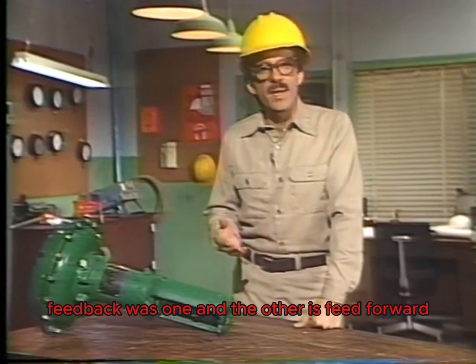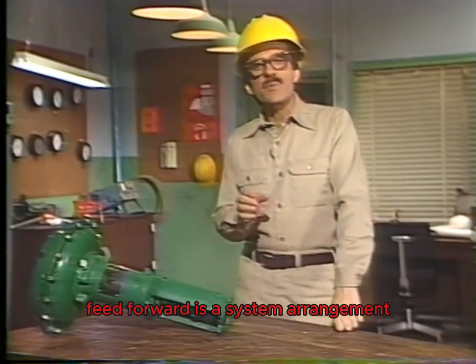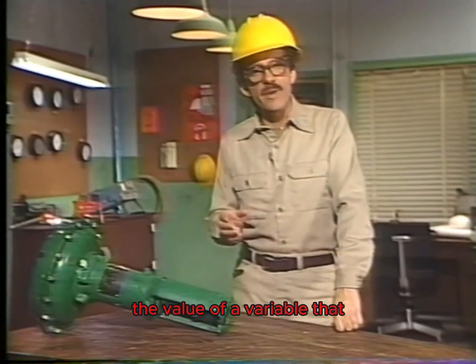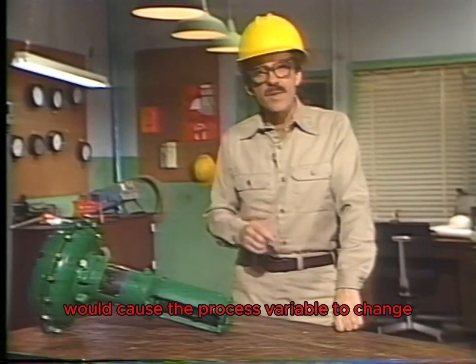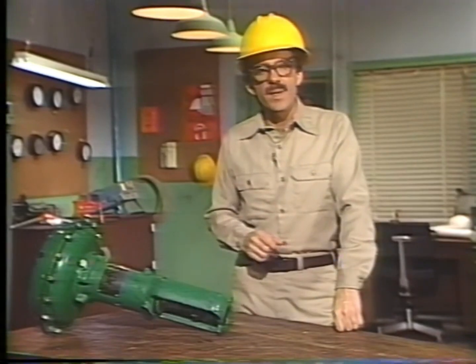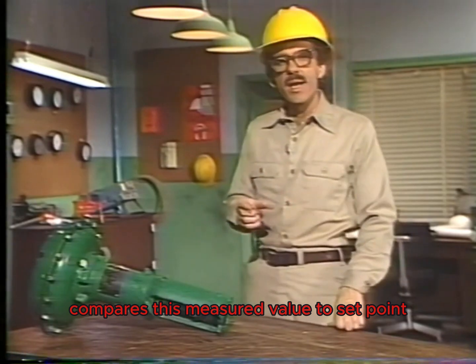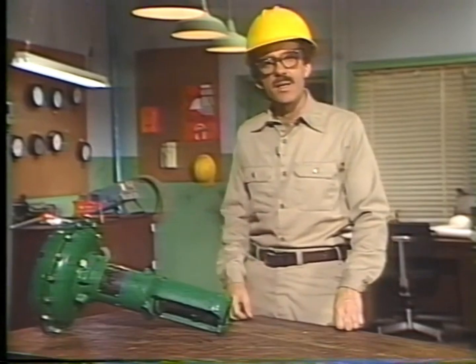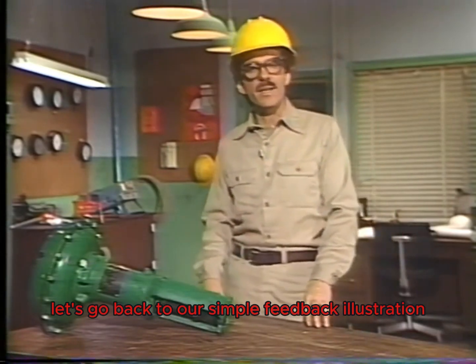Feedback was one, and the other is feed forward. Feed forward is a system arrangement in which the system continuously monitors and measures the value of a variable that, if not corrected, would cause the process variable to change. The feed forward system compares this measured value to set point and takes action to prevent the process variable from changing. So to see how this is done, let's go back to our simple feedback illustration.